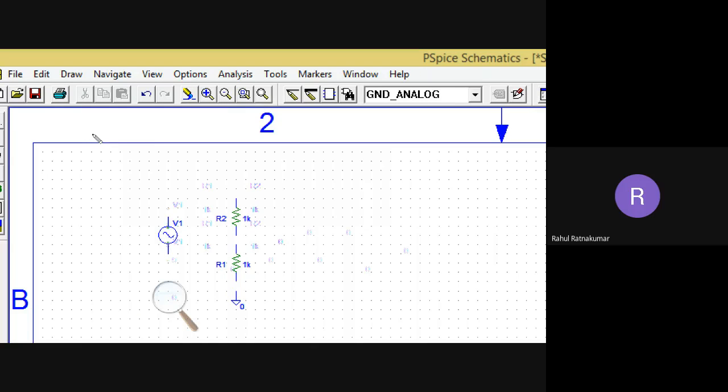Okay. So now I'm drawing the line, the conductor. So it will be like this. Okay, like this. Are you able to see I've drawn some lines from the V source to the resistor R1, sorry, R2. Again, I connect this R2 and R1. Just click where you want to start, and just click where you want to end. Now the connection is there.